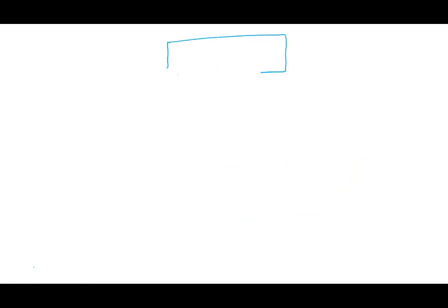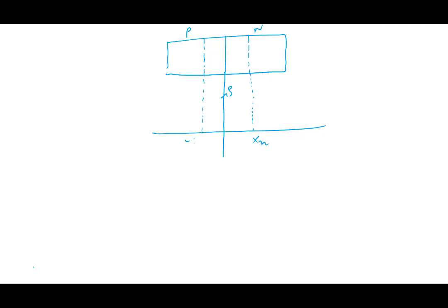Okay, so let's see. I'll stop after this. So the PN junction is, let's say, here. All of you realize that there's a region now, which is the depletion region, or space charge region, whatever you call it. Can I now, in this region, draw rho? Let's call this edge of the depletion or space charge region xn, and this as minus xp.